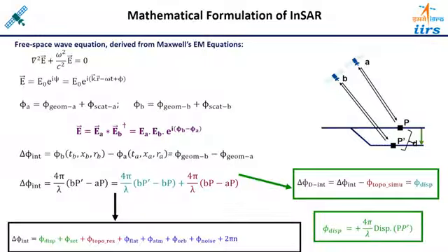So keep in mind, this particular interest requires the optimal removal of the other components. At the same time, keep in mind the phi noise cannot be removed. It means the contribution of phi noise will always be there in the interferometric phase, and you can consider that as a displacement phase. So whatever displacement or deformation you are calculating from the interferometry, the contribution of noise will always be there, but you have to quantify how much noise is there in the data set.